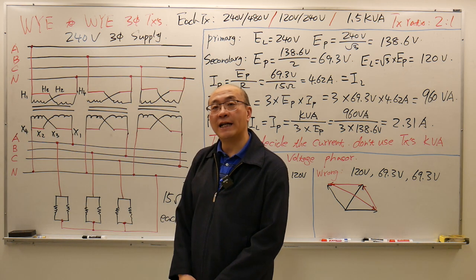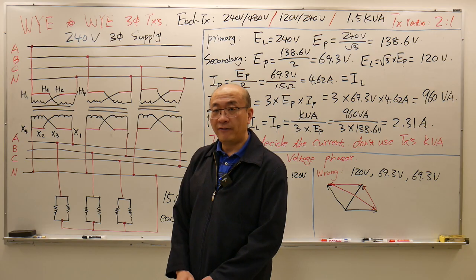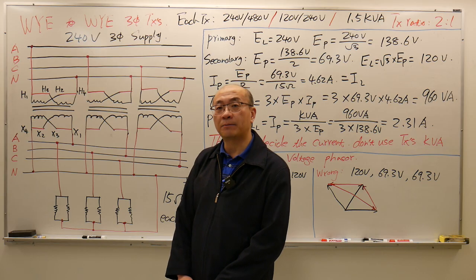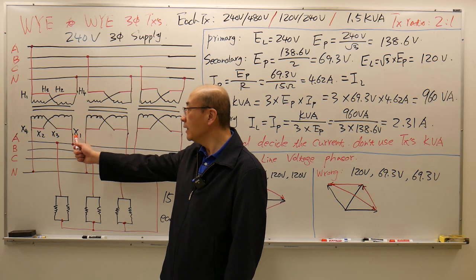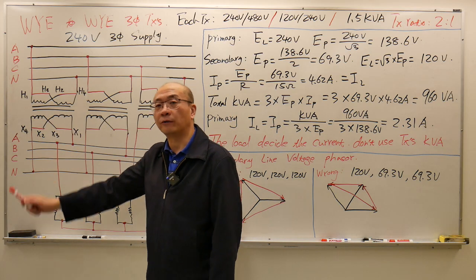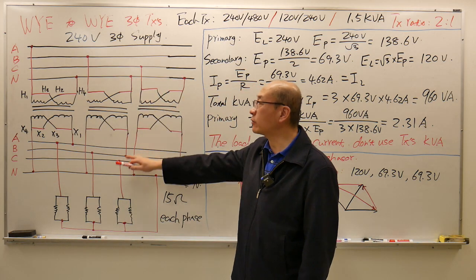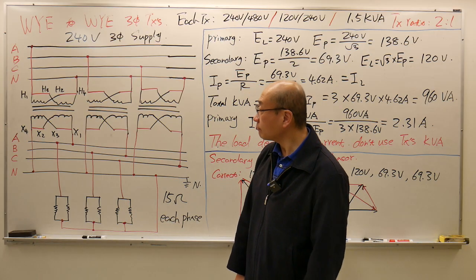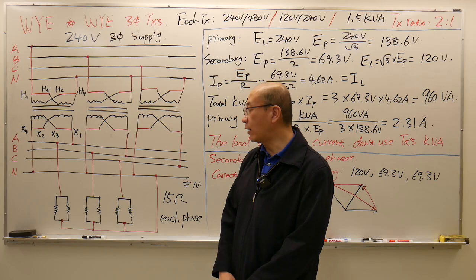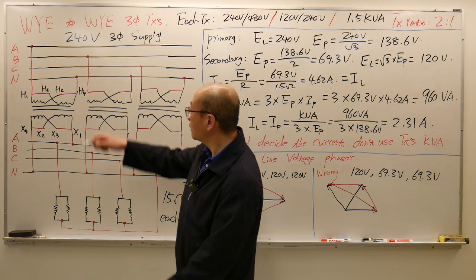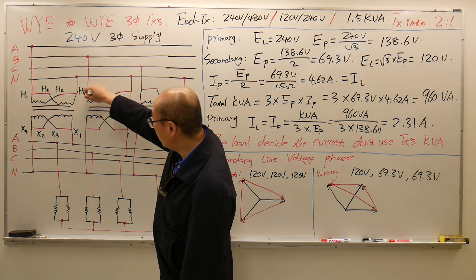And by following CSA phase displacement, a Y to Y transformer has 0 degree phase displacement. So H1 connects to line A, H4 connects to neutral. I connect each of the phase transformers in the same way. So here's the connection diagram down here. I think somehow this line got erased a little bit.